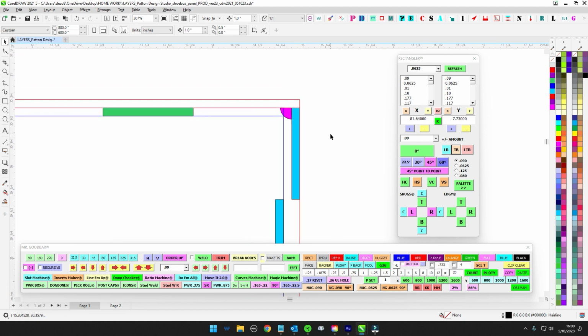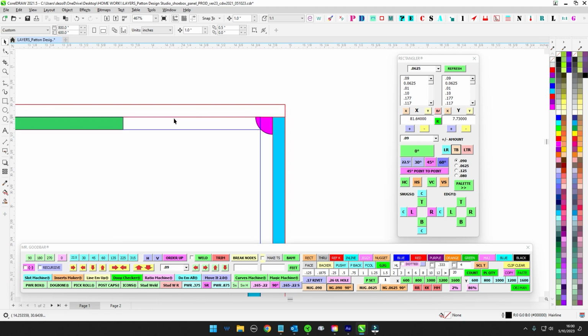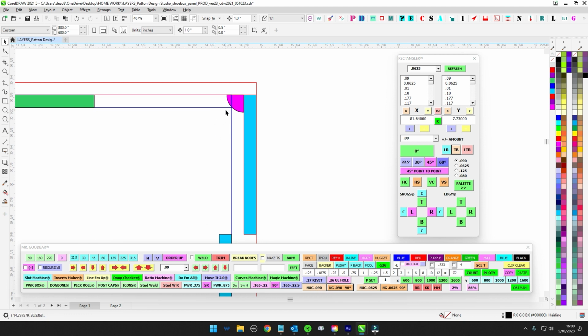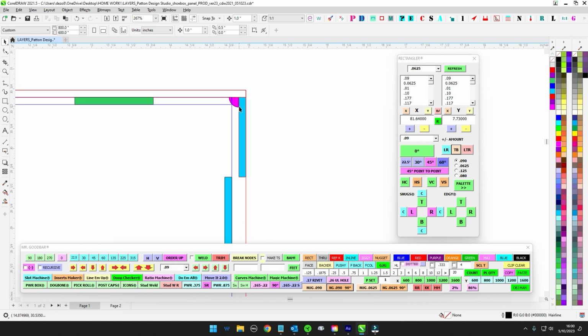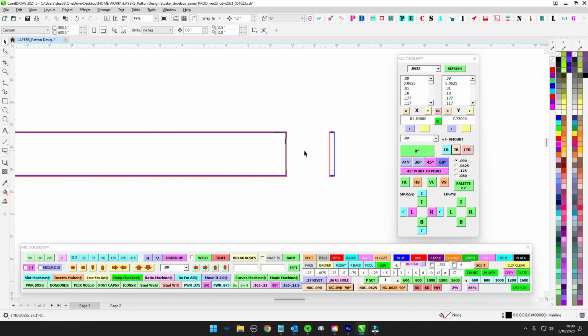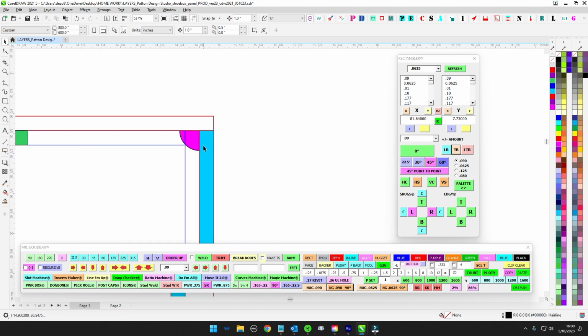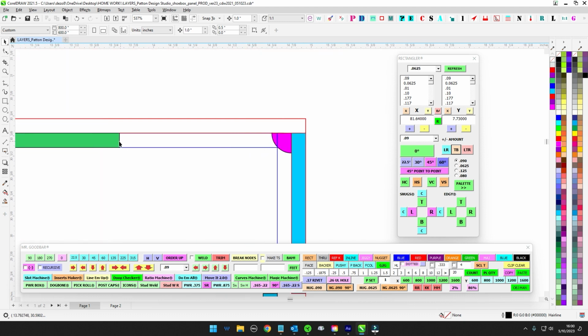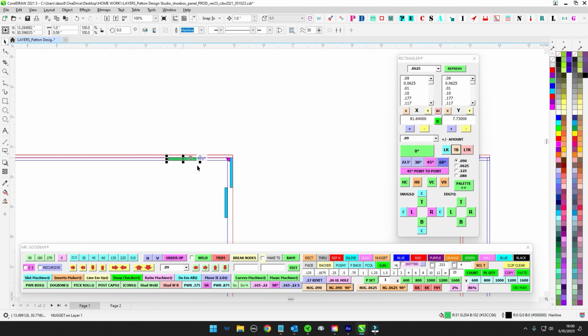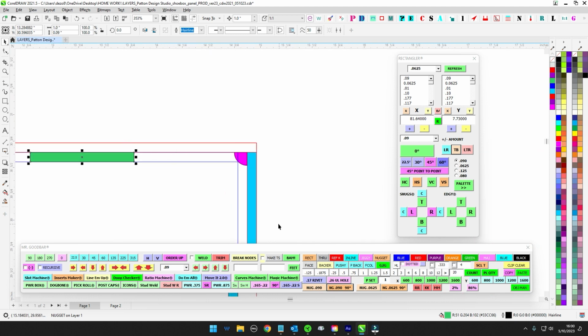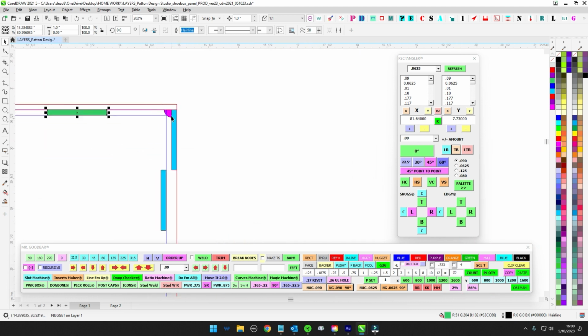Keep in mind that I like to keep at least a 1 inch no fly. 3/4 is pushing it, but you're going to have heat affection. It's going to be warped. You're going to have little boogers and little snots and stuff all over, little pieces of metal. Also, this is a non-illuminated one, but if this were illuminated, then we would also have sealant. We'd have caulk here. It'd be built up. It could get in the way of this here. So you want to make sure that you clearance these corners, basically clip them in order to clearance for welds.